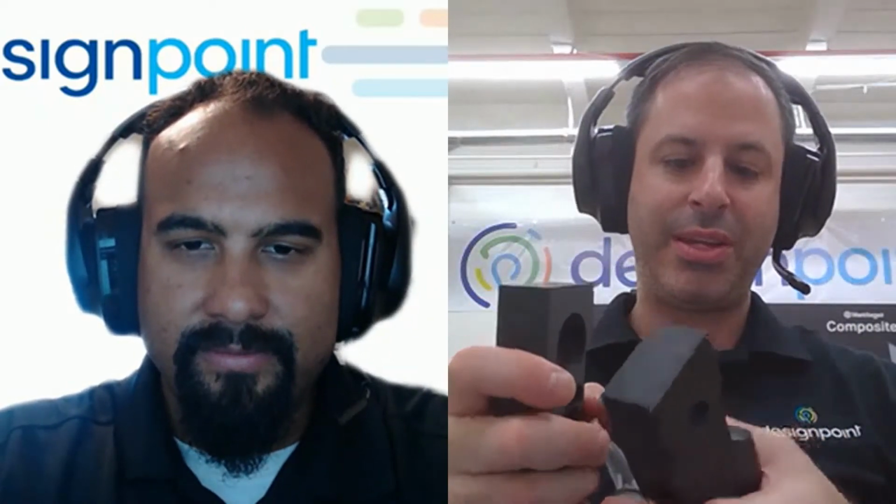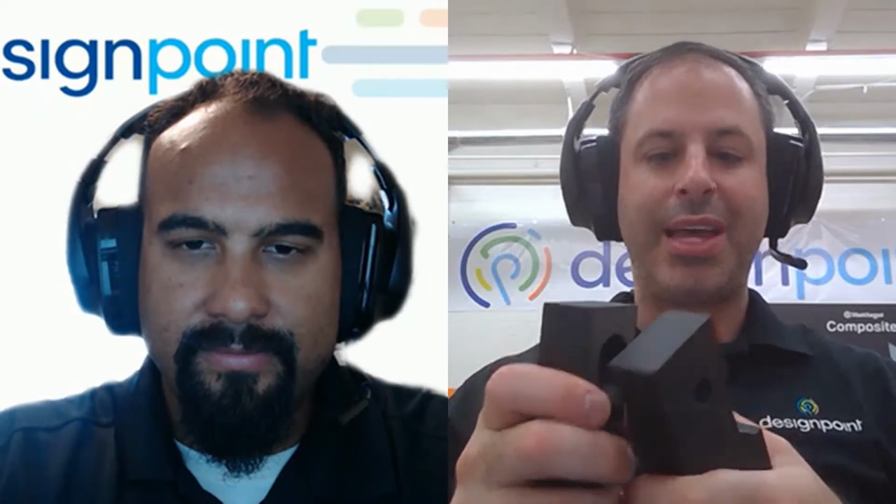So especially for an application like this, like a set of soft jaws, they might be pouring cutting fluid on top of this as they're cutting this part. So it has to be resistant to chemicals. So that's why I like this Onyx material. It's good in a lot of categories as far as being a rugged plastic that's good for manufacturing. But then it gets even better when you put in continuous carbon fiber, like this part has.